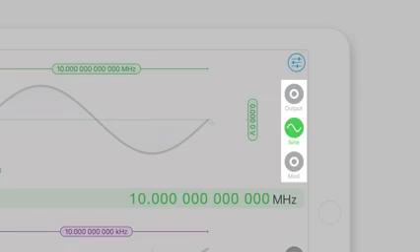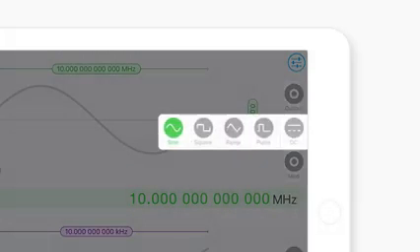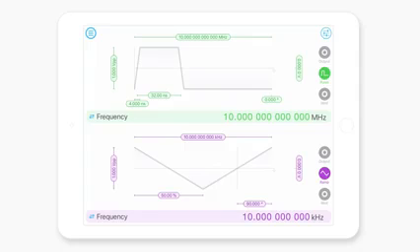These allow you to quickly activate and deactivate each channel. So up the top, if we wanted to activate the sine wave on channel 1, we just tap that icon and that will be generating an analog voltage at the output. We can deactivate it by tapping it. We can change the waveform by selecting from this little menu here. So if we wanted to generate a pulse wave, what that'll do is change the little illustration on the left and bring up a couple of new parameters for us to tune, which is edge time and the pulse width.